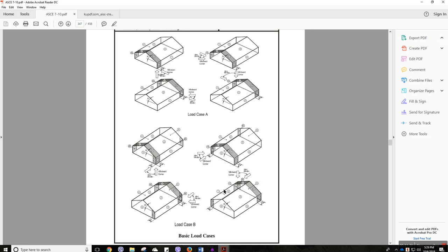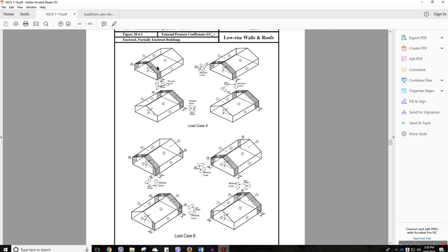The 8 different cases are, I can show you here. First you are putting the A here, 2A here, right? And again 2A over here, and 2A in the same location but from the opposite direction, and in the same way for the other one. So 4 cases over here, and go to the other axis and 4 cases over there. In total there are 8 different cases of the wind load, but here I'm just going to show you only the first case, but the others are similar. You can just calculate the 2A in the similar way and apply the wind load.